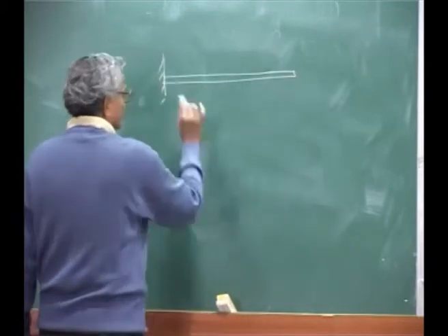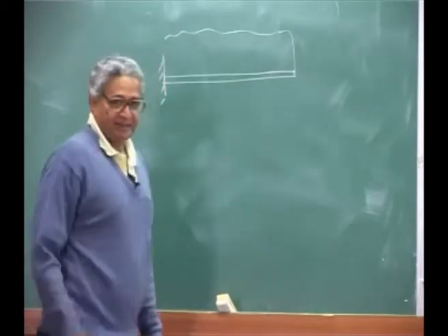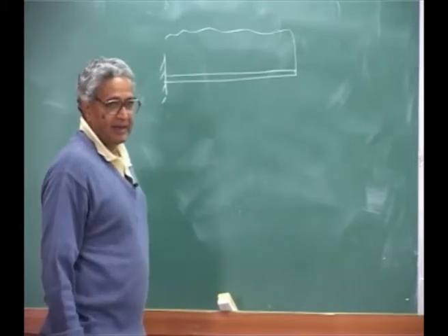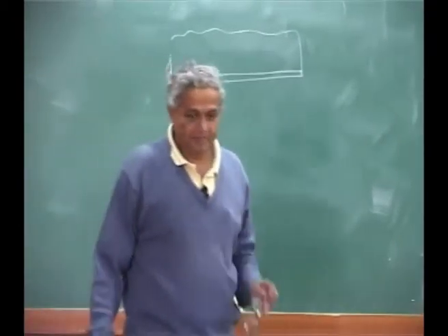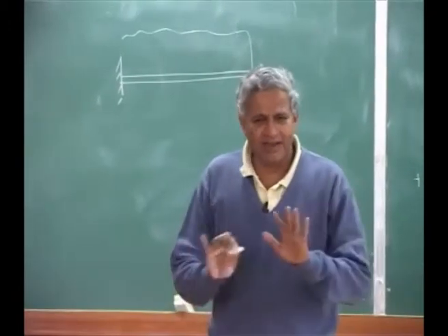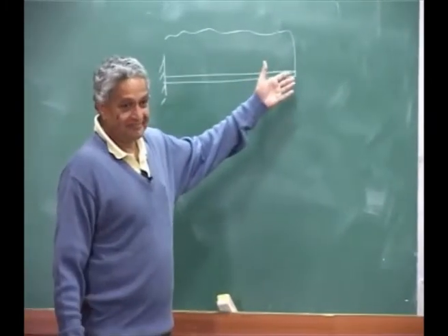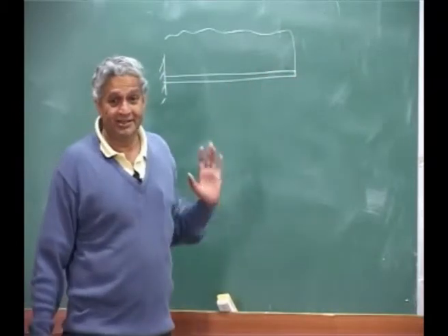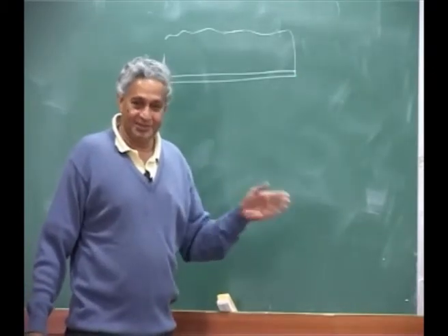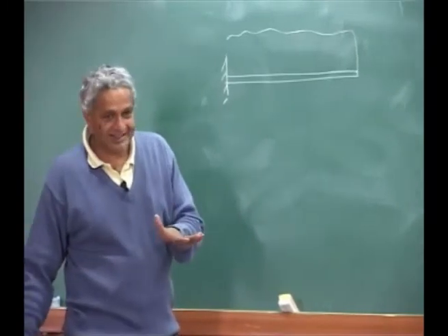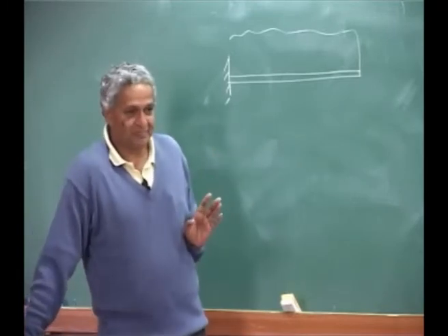And you have some distributed load which you may put like a wing loading kind of thing, and then apply all these four methods and get just a static problem, deformation of the beam at any point, using direct collocation, collocation with assumed mode, then Galerkin, then Rayleigh. All the four techniques.